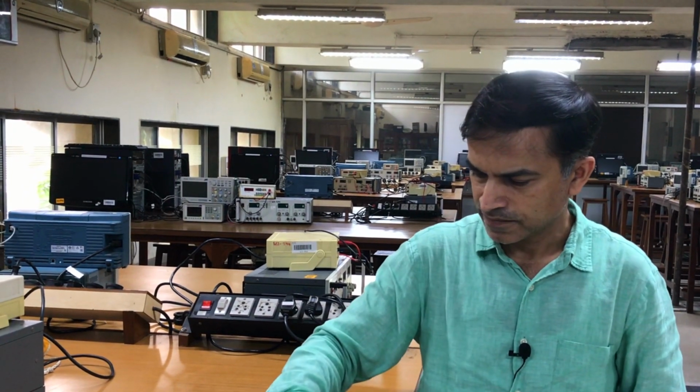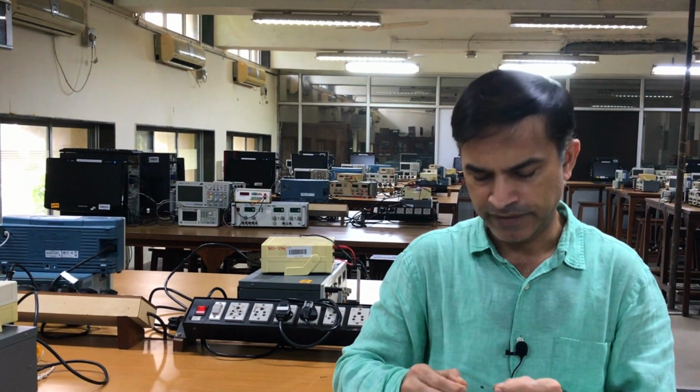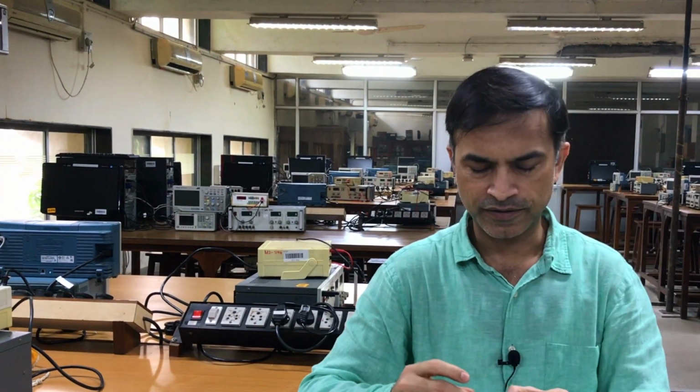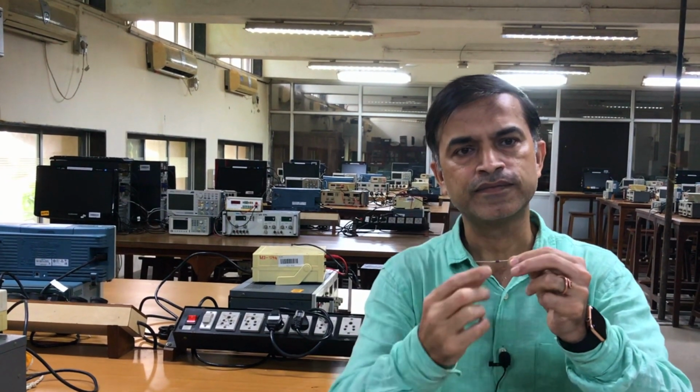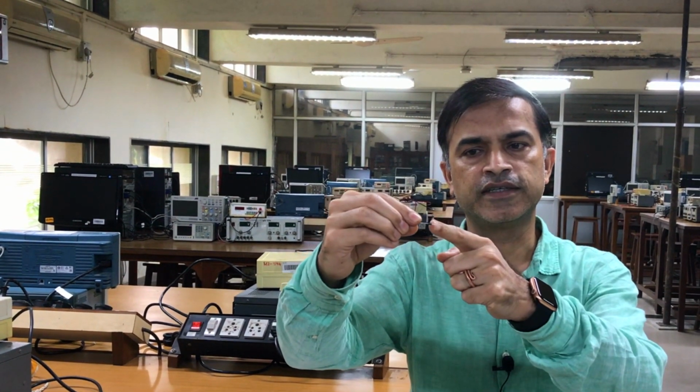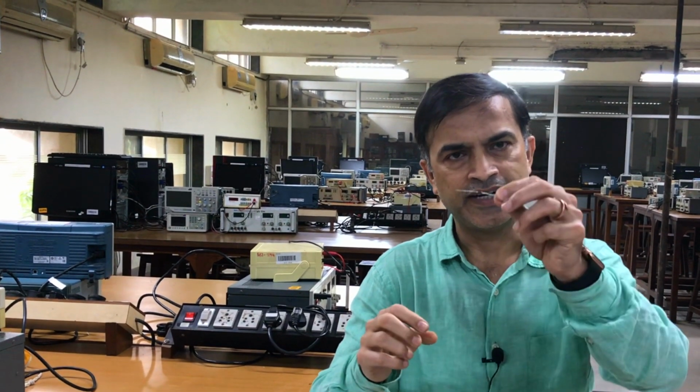The first device we're going to talk about is the PN junction. Here I have a PN junction diode that I would like to show you. If you observe this diode carefully, when you're back or if you have a chance to look up one device, you will see a ring around the device on one side. Generally, whenever you see that ring, for example in this device the ring is on the left side, that is the cathode of the diode. We have anode and cathode. Anode is the positive terminal, cathode is the negative terminal, and the ring indicates the cathode.